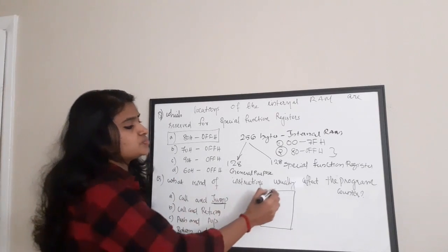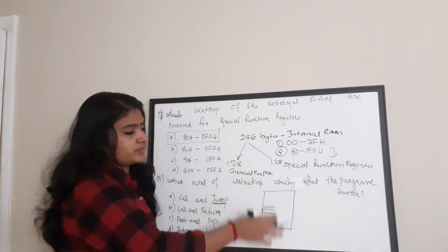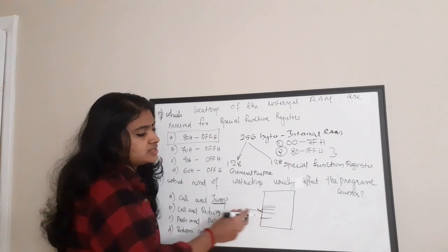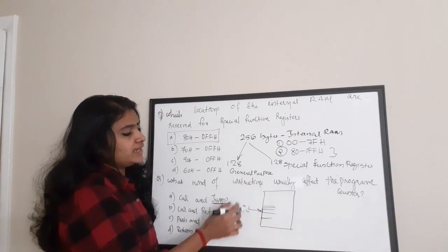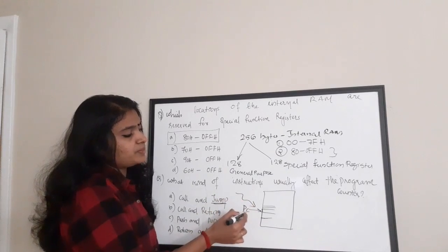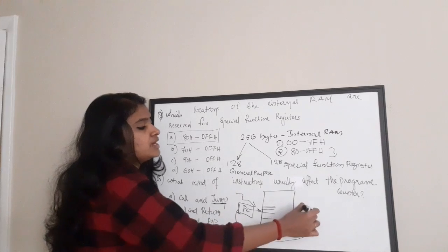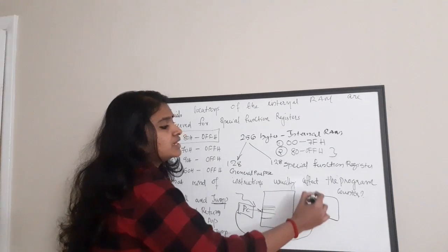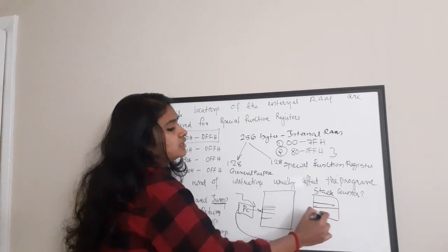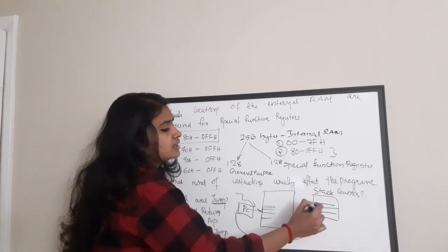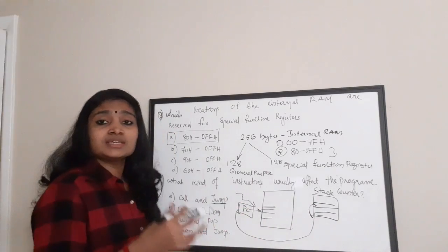Okay, so when the processor is executing some instruction in the current program, while executing this line the program counter is here. An interrupt comes. What will happen? The address present in this program counter has to be saved to a stack, that is a stack memory. It has to be saved to the stack in order to use it back when the interrupt processing is complete.